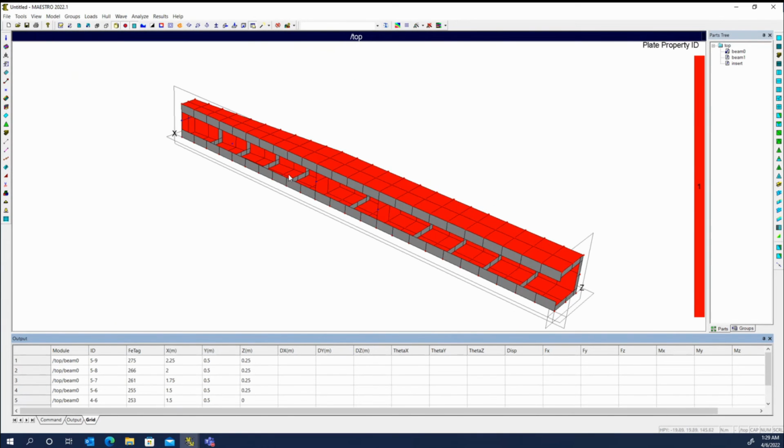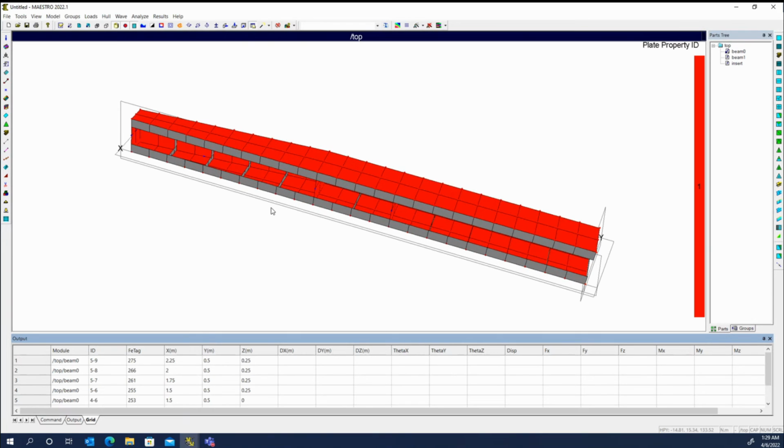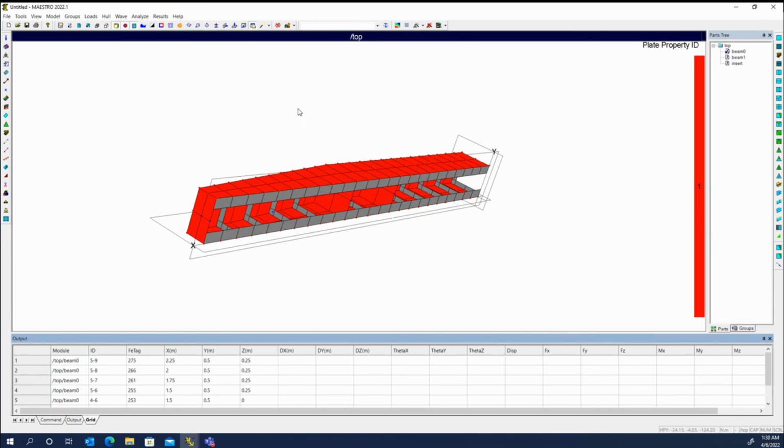Likewise, we can look at our plating. Now, we only used the 5mm AH36, but there were other options available. Now that we're in this dialog, we could use the dynamic query and actually change that to put some 12 millimeter at the end here. I think I missed that one. I made that 8.